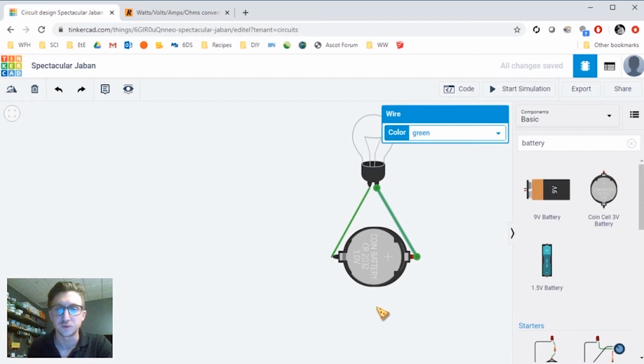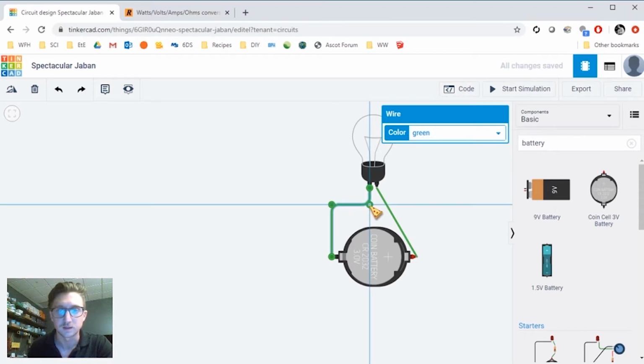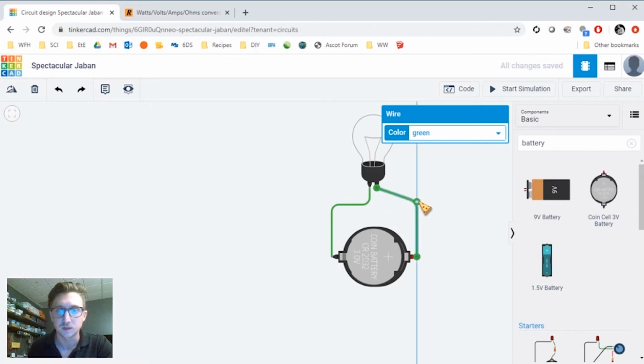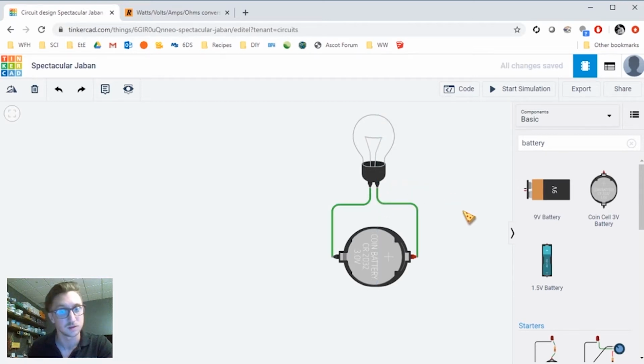Now, I don't know how you feel about the way these wires are sort of arranged, but it seems a little awkward, seems a little tight. So what you can do is actually add a bend to that wire. If I double click right in the middle of that wire, that little point shows up. You see that? And I can arrange it so that it's straight up and down like that, and maybe I'll add another one right here. So it's nice and square. I'll do the same thing on the other side as well. Add 2 points, so all those wires are nice and square. Ooh, that looks pretty nice actually.